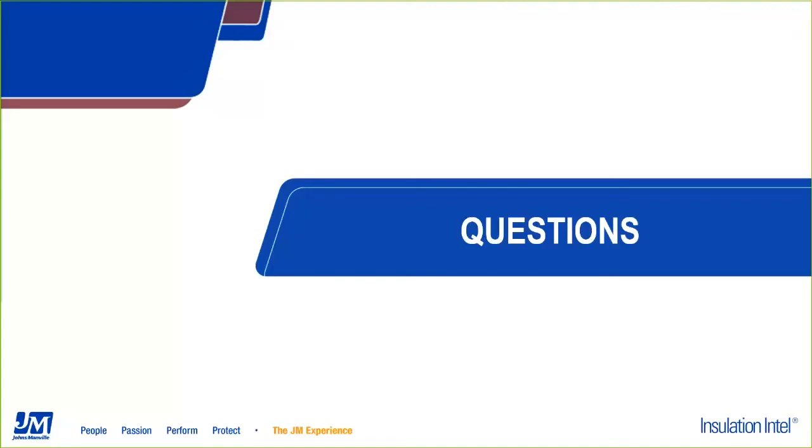So there's various fastening methods. A couple of points to keep in mind with that exterior fastening method. The reasoning for the continuous insulation is to cover up the metals that are basically thermal shorting through the system. So there's some fastening methods.